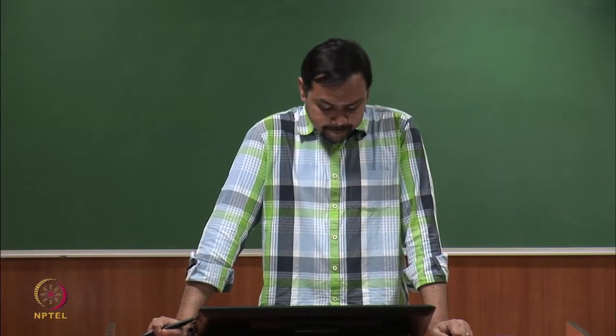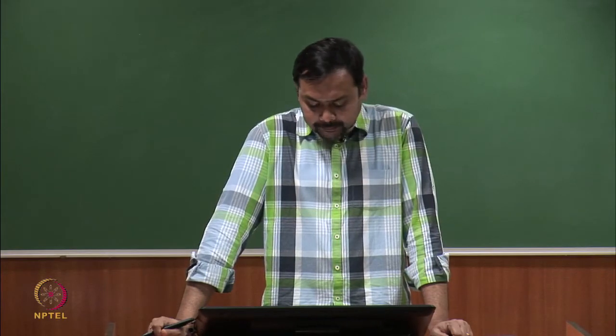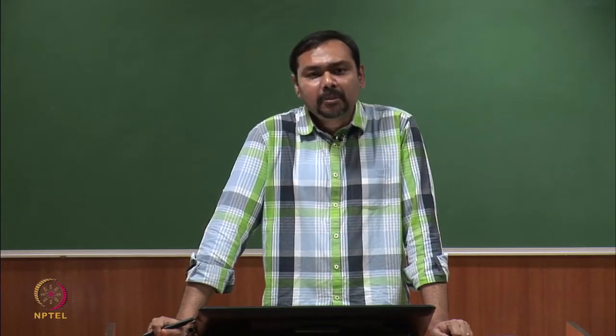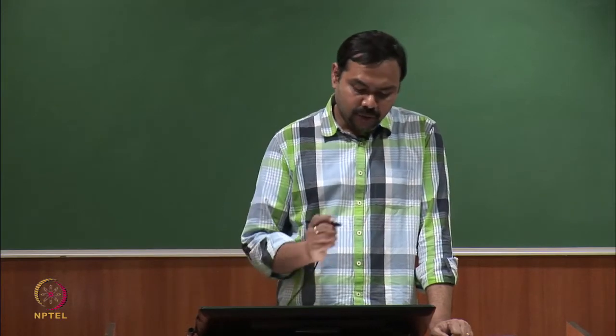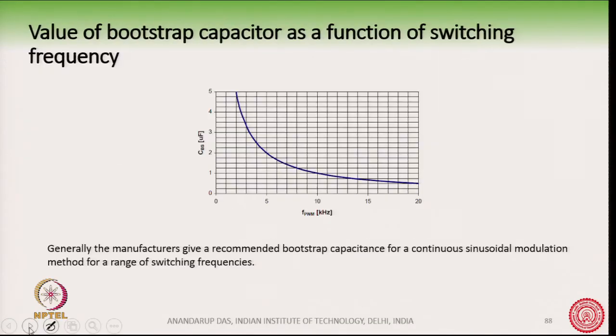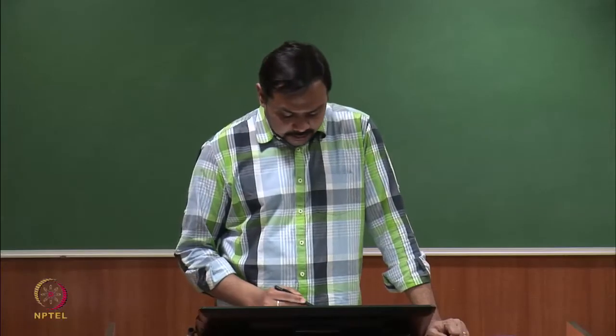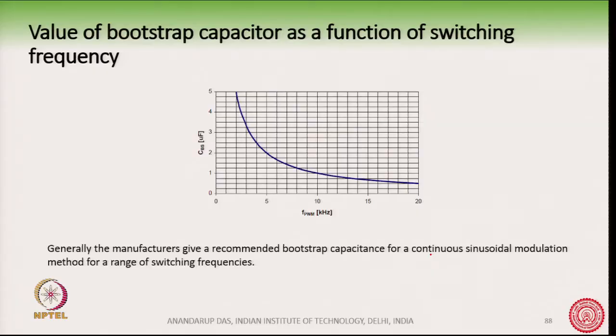So, you can take 1 microfarad capacitance, and the bootstrap capacitor value can be selected a little bit more than this, maybe 2 to 3 microfarad, okay, and this works quite fine. In fact, some of the manufacturers give a recommended bootstrap capacitance in their data sheet. They will give a recommended bootstrap capacitance depending on the PWM frequency.